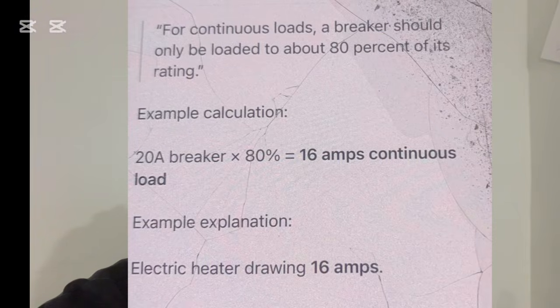In the case of equipment wire, flexible cord in sizes number 14, 16, 18, and 20 gauge copper and tinsel cord, which are considered protected by a 15 amp or 20 amp overcurrent device.